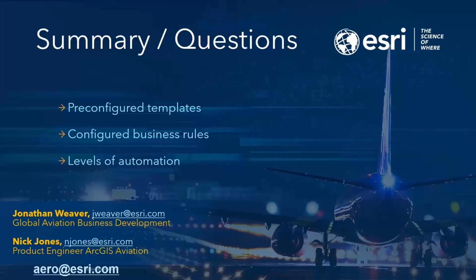Next question is a bit of a migration question. If you are a user in ArcMap and you have masking rules, do we need to recreate or migrate those over to Pro? Again, the short answer on this is that they will need to be reconfigured. They're put together a little differently than they were in our ArcMap solution, so there's a bit of effort involved in doing that. But in Pro, there are improved capabilities that allow us to better define the masks themselves and make them a little more efficient.